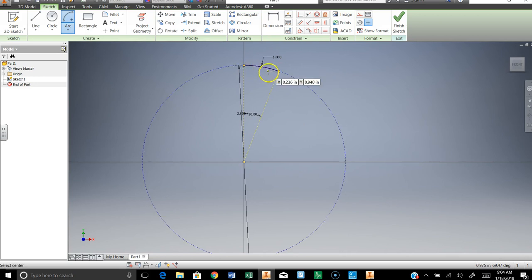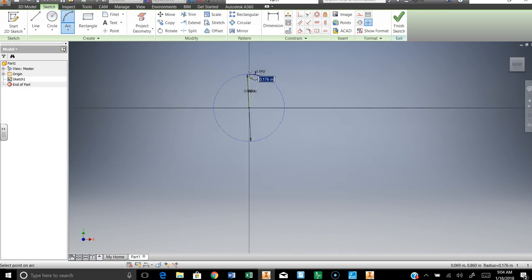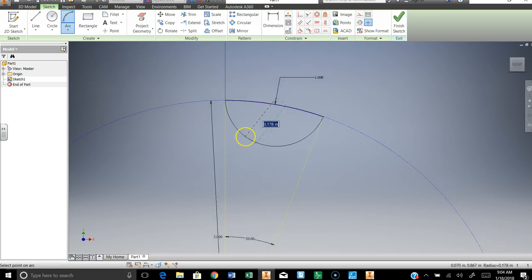right from there to there. Now I'm going to make a second arc, except this arc I'm going to make using 3 point. In other words, I click on my 2 end points of my arc. So I want one end of the arc to be here. I want the other end to be over here, where this line ends, this arc ends. Notice, now I can decide how big of an arc I want by moving my mouse. But what I'm looking for here is this. I'm going to move it in until there. You see how, I'll zoom in. You see how the tangent signs pop up on the right side and left side there? I'm going to move it until I get that symbol. And then I'm going to click.